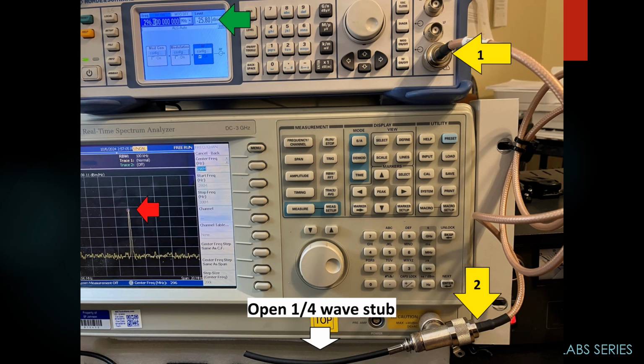I add the quarter wave stub. Now look at the green arrow. I have not changed my generator output at all, but my red arrow has dropped. Each division on the scope is 10 dB. I'm down about 32 dB. I'll give you the math later on, but that's a tremendous improvement.